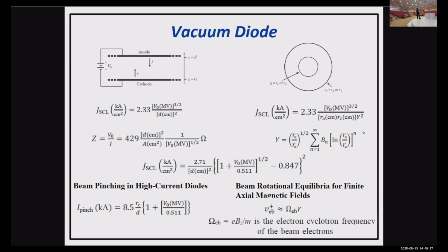Also, there is rotational behavior, as I was describing. Now, this rotation is going to be the cyclotron frequency for the whole beam. That's why we use a big omega, the whole beam is going to be suffering from the cyclotron frequency. If you are designing a backward wave oscillator or other devices other than a gyrotron, this is a negative thing that you need to reduce.